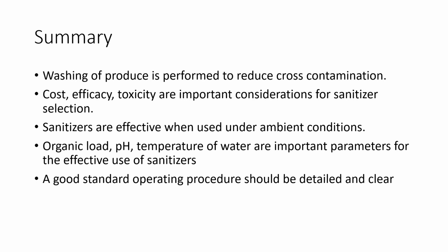Parameters such as organic load, pH, water hardness, and temperature are very important to be monitored throughout the whole cycle where a sanitizer is used. A good standard operating procedure should be detailed and clear.